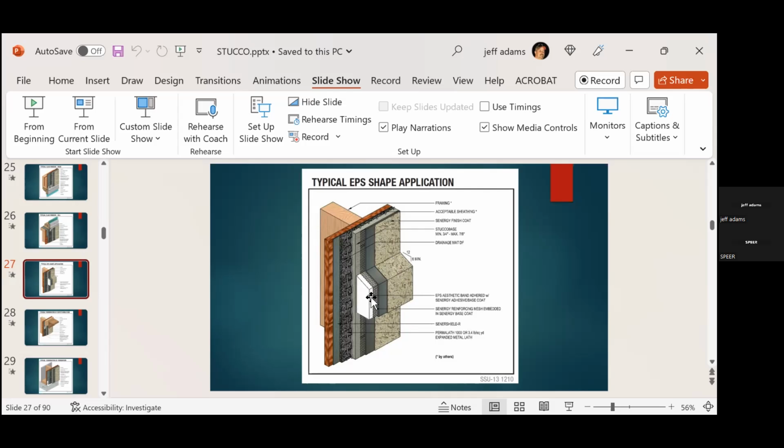When they put the foam on there, they're nailing it, putting holes through there. It's not covered by the WRB. They just put a polymer top coat over the top of it to make it flow with it, and the water's going back behind here and being trapped in there, following the fasteners in and so forth. These products are not going to be nailed on. They're going to be adhered with an adhesive to hold them on and so forth. This is a huge failure aspect of most all houses that have decorative bands.